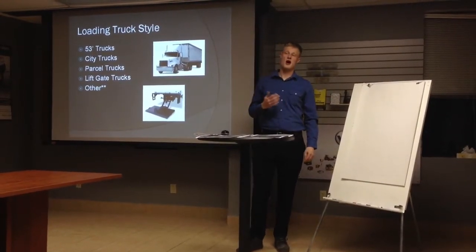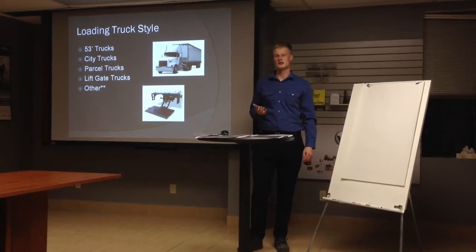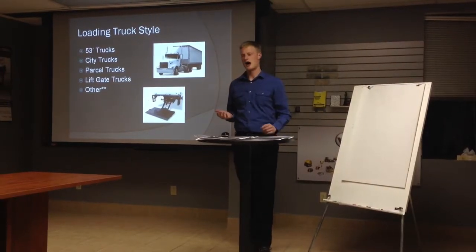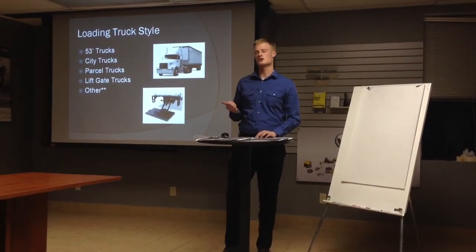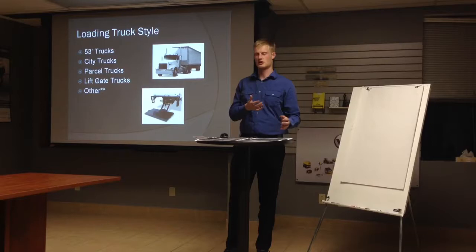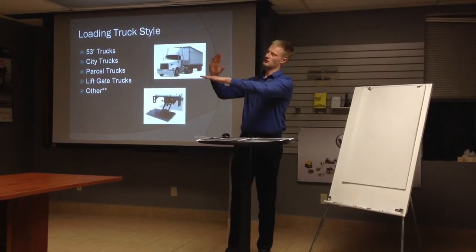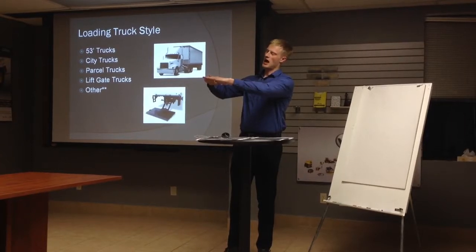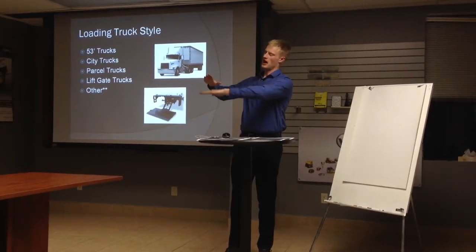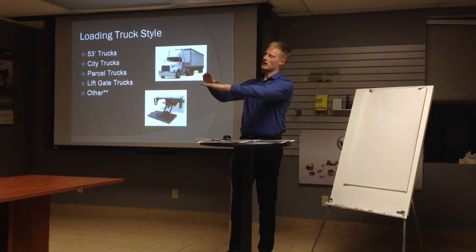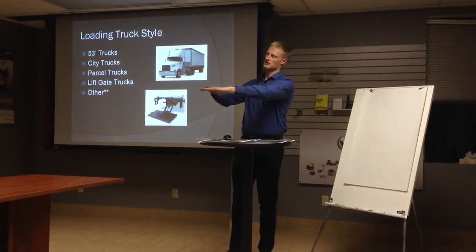The thoughts when looking at trucks and the design of a dock is, as I said, the height at which that truck comes in, and how close that dock can get to the truck. In essence, we have a dock lip that will need to reach the back of a truck. And we also have not only the distance away, but the height of that. So when designing your leveler, you must design a leveler that will accommodate the height of that truck and the distance away.